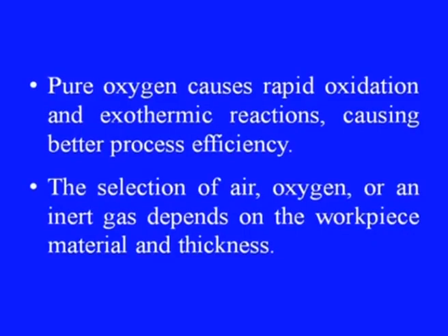Pure oxygen causes rapid oxidation and exothermic reactions, causing better process efficiency. The selection of air, oxygen or an inert gas depends on the workpiece material and thickness.